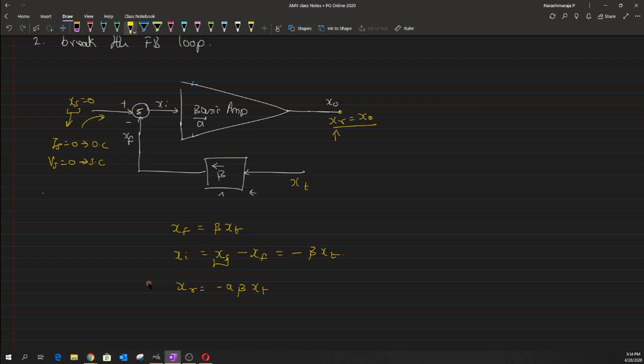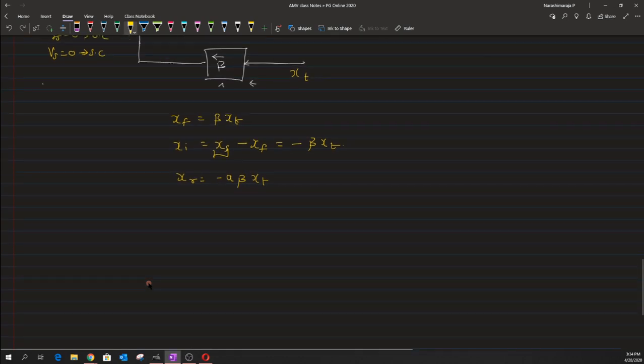and it follows that the loop gain given by the negative, yeah. So, let me write this. So, in this case, the loop gain can be written as A beta, and that is nothing but it is written as a negative ratio of the returned signal to the applied signal xt. Okay. And it should also be obvious that this applies regardless of where we exactly broke the circuit.